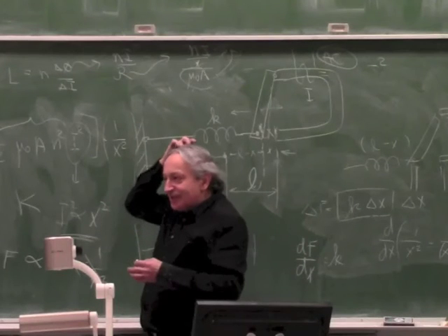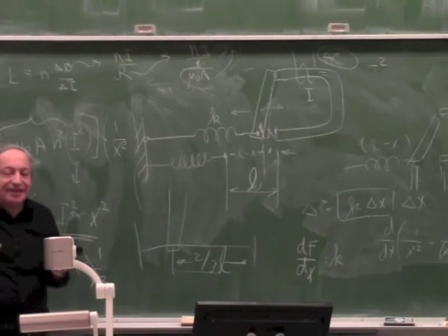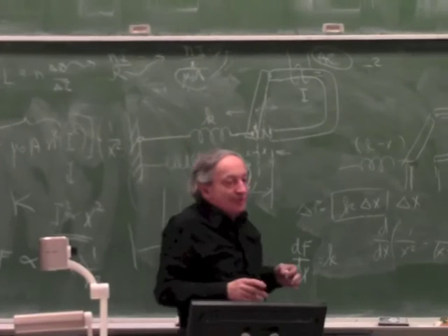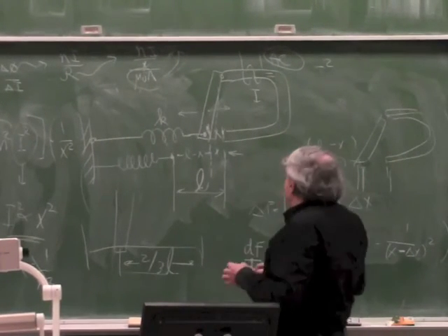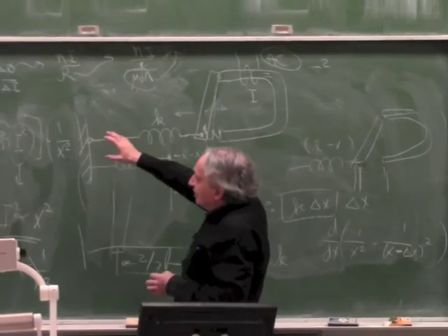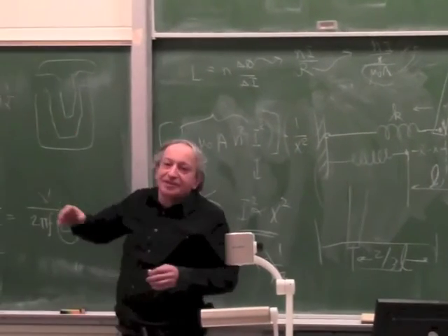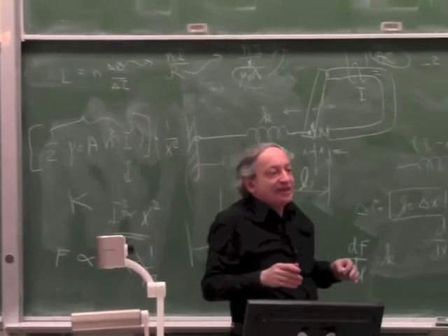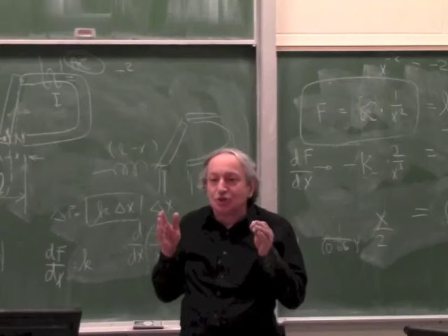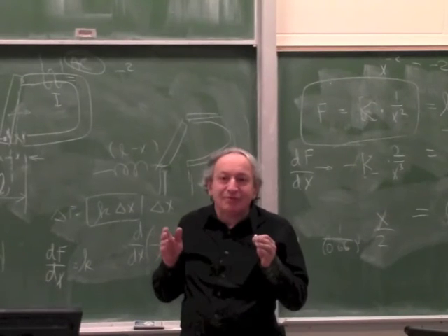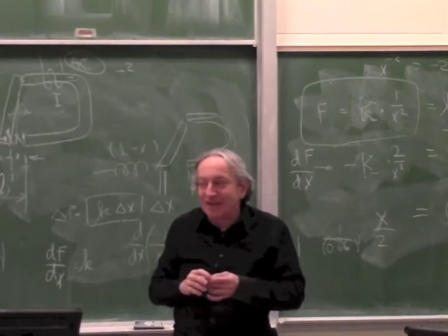Now the reason this doesn't happen is this whole model relies on linearity, and we learned before when you have magnetic materials they saturate. So this model that says that we can cancel out the nonlinear behavior by running it from AC only works if everything was linear. In other words, it works if we had a very big air gap. If very big air gap, there will be no saturation. But then we are wasting a lot of the travel of the actuator and a lot of the potential force if there's a big air gap.